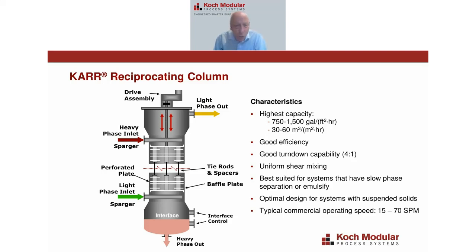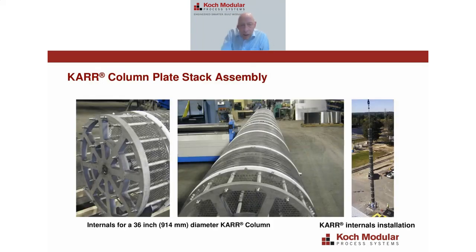The whole plate stack moves, so it doesn't really allow any place for the solids to build up. This is a good picture of some plate stacks for Karr columns. In the middle here, you see this column. It was about 36 inches in diameter, and it has a whole bunch of different plates on it. You look to the left here, it has a perf plate, which my arrow is showing right here, and you can see again high open area, large holes,